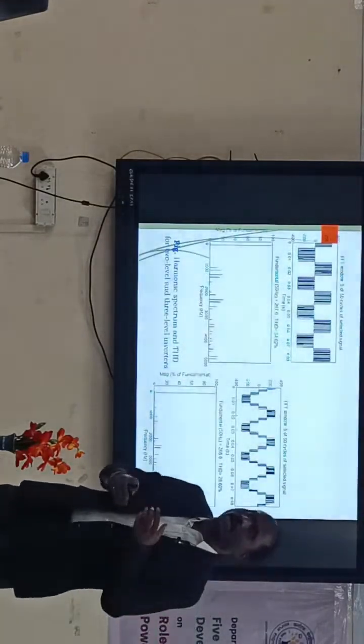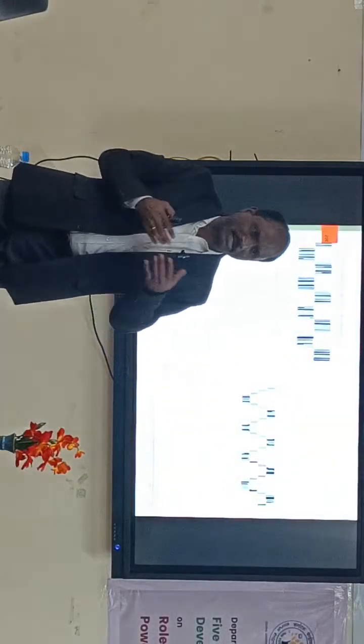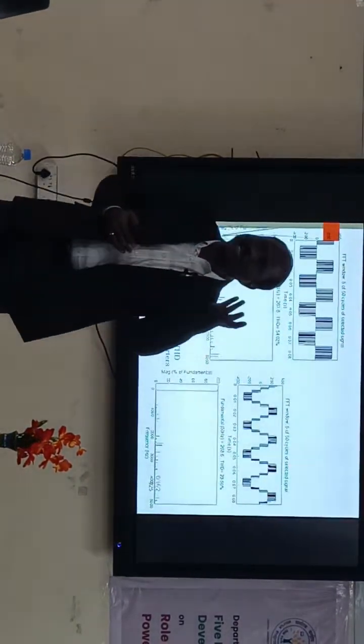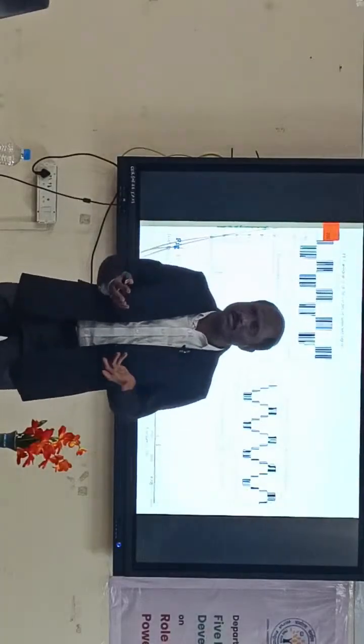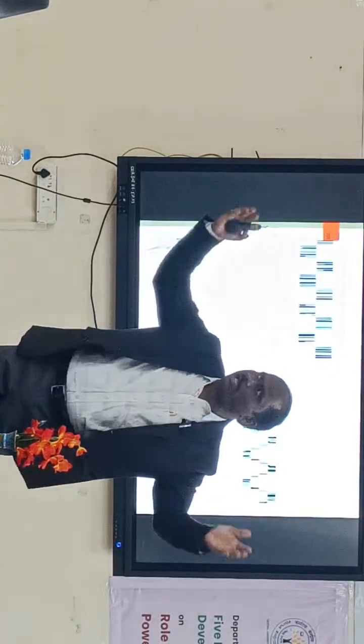So for that, how do we calculate these time periods? For 3 levels, somebody has done some mathematical calculation and got the time periods. But if you go for 7 level or 99 level, I implemented 99 level. How is it possible to find these time periods? And the controller also has to recognize what the sequence is. For that case, we developed different algorithms to simplify it. For higher levels, we simplify it like a 2-level inverter, and then we operate that. Okay, in that way we have done.